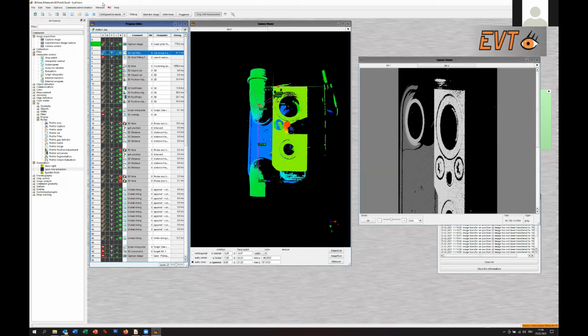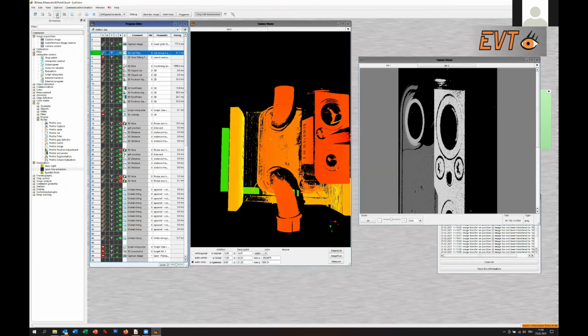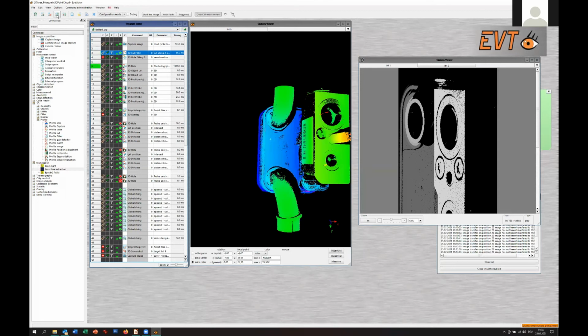Of course, on the top you see a cyclic execution, a single time execution, or a step-by-step execution. If you press this one here, the tool will go to the next step, and you see the program counter, so that you can see what is executed right now.